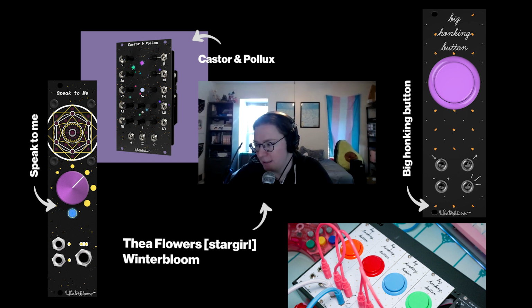Another thing that I can point out on Soul is that I was still getting used to surface mount stuff. So I ended up using larger resistors and capacitors like 0805s and 1210s. While those are a lot easier to solder and deal with, they are also more expensive.